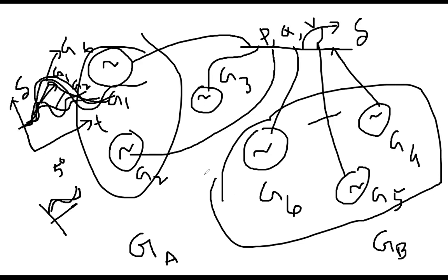The benefit of this method is that it will reduce your computational burden. This means you will be treating their inertias together. Like one has inertia H1, another has another inertia, you just sum them up. Because this is my new equivalent system, a coherent group, I have one combined inertia.